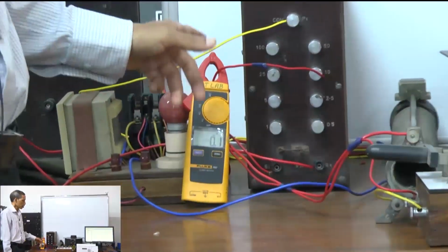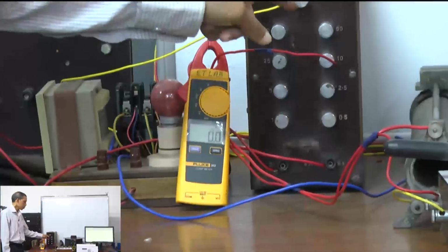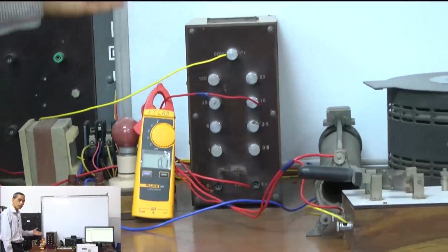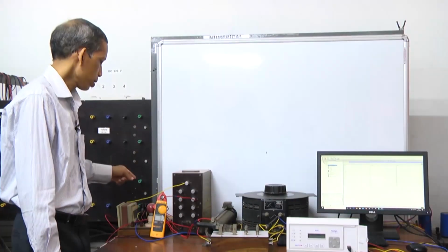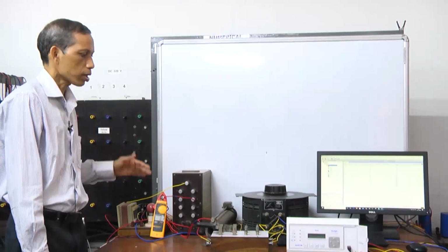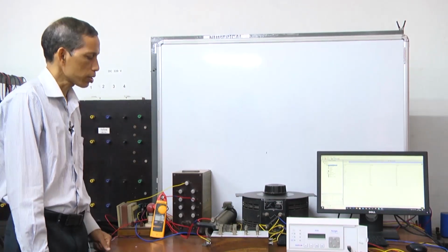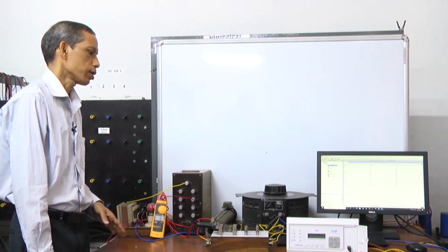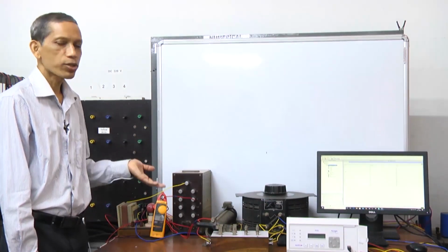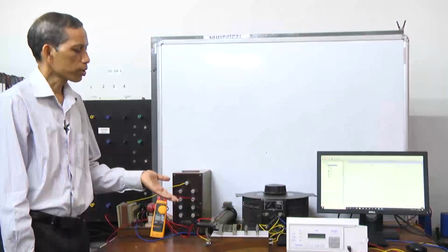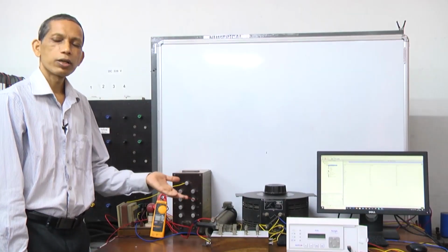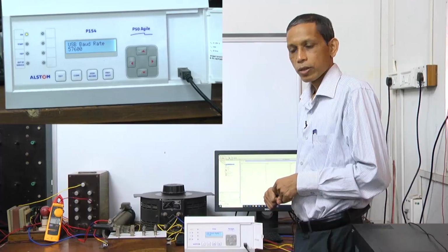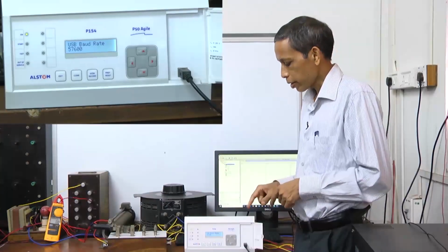Knowing this current, we allow the fault current to continue, and when the fault current exceeds the pickup setting, the breaker opens after some time depending upon the relay characteristics, and the faulted circuit is isolated. In the next step we will demonstrate the fault, and before that we will talk about the settings of the relay. So, now we will see the relay details.